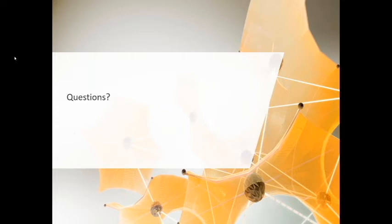Looks like, does the job processor still consume a Vault license? No, it doesn't actually. I think that changed either in 2019 or 2020. The main thing is the Inventor license too there. We want that to be able to work without consuming a license, because it uses Inventor in the background. There's a read-only version of Inventor that can get used for that. So no, it should not use a license to do those tasks in the background. And I believe that was the only question right now.